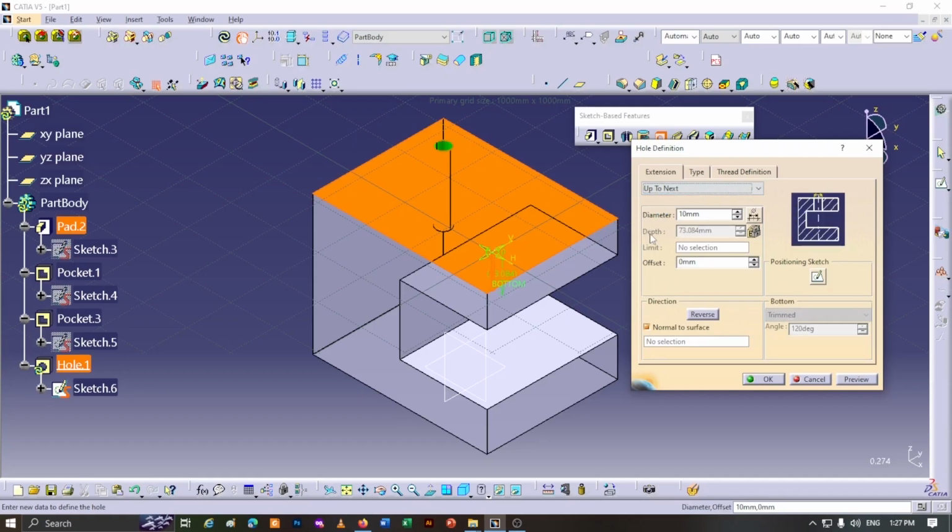You see that the Depth option became inactive. Another option called Offset is active. Our schematic shape also changed. In the schematic, you now only see a diameter dimension. The software moves the hole to the second opposite surface and creates it.